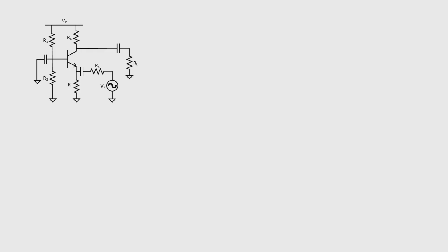You can see that in this drawing, we still have that capacitor attached here to the base that provides an AC ground. Let's draw the AC equivalent circuit at this point to see what it would look like if you were the AC signal traveling through the circuit. We'll start at the source, so I'm still going to have my AC source V sub S. The signal then passes through resistor R sub S, and the capacitor appears as a short circuit from the perspective of the AC signal. We then have our emitter resistance R sub E, and our little emitter resistance little r sub e inside the transistor. The base is grounded, and it's grounded only for AC signals.